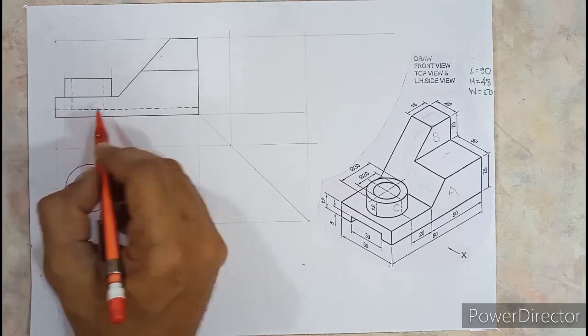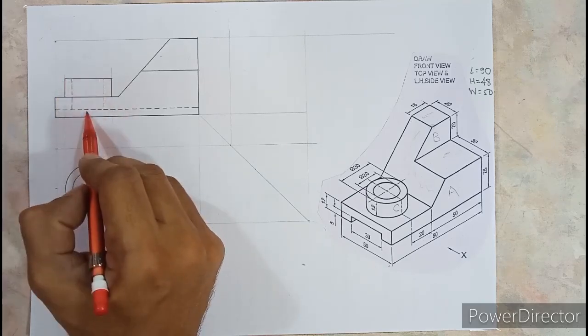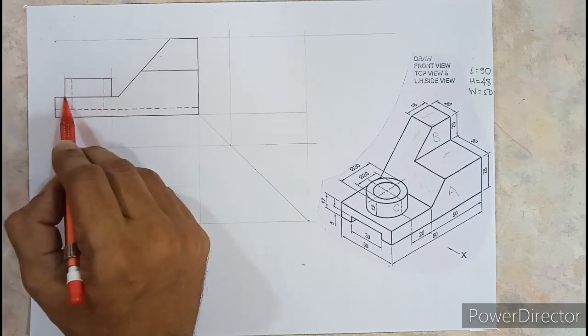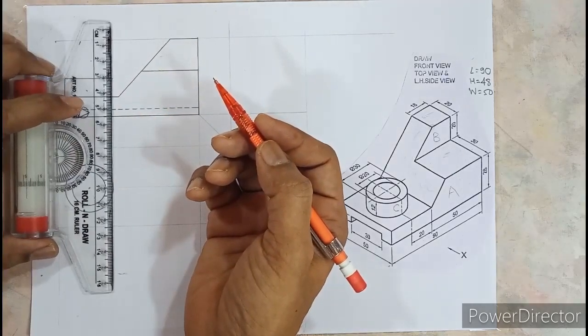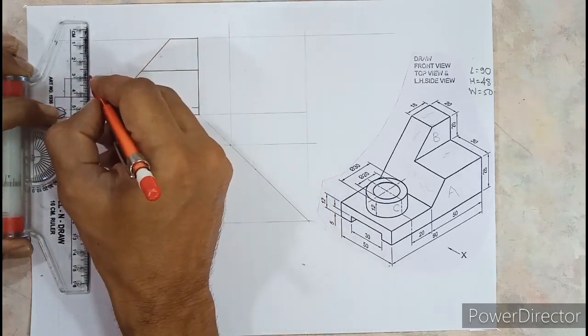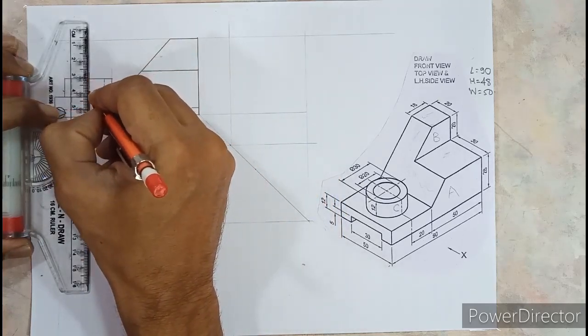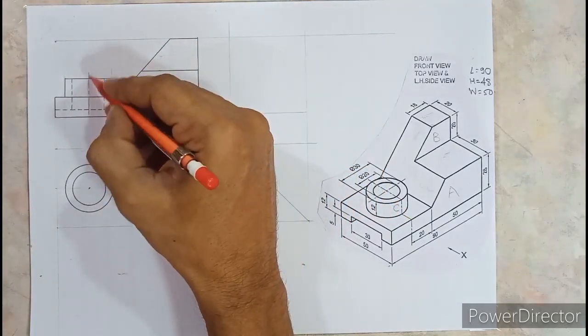This is the slot. Now as I told you, whenever you draw a rectangle without axis, it means it's a flat surface. But this is not a flat surface, it's a circular surface. So what we need to do is, we need to draw a medium dark axis line. Medium dark axis line means it's a combination of big dash and small dash. And now see, be careful. See this axis line I have drawn, right?